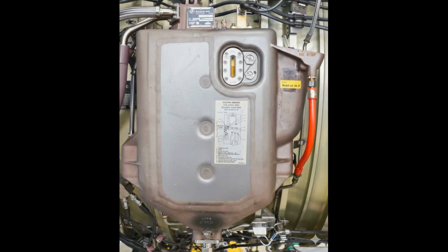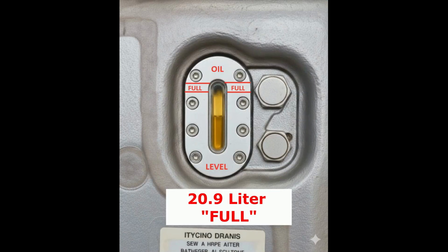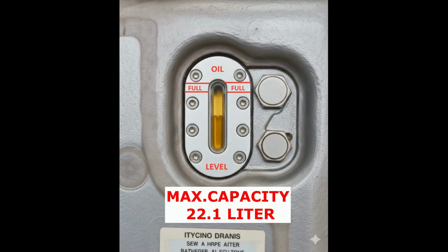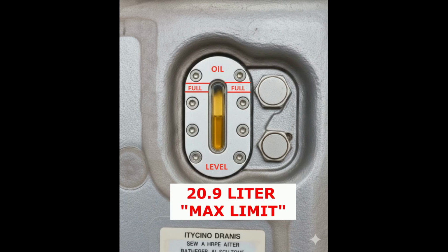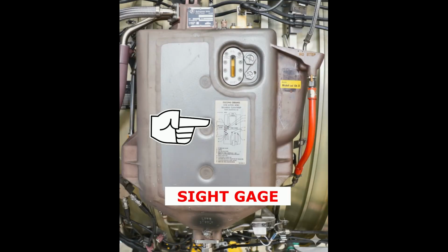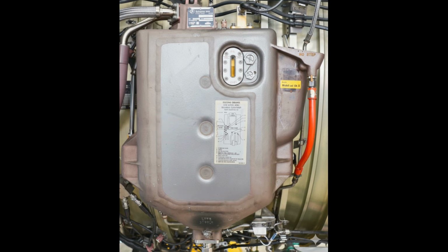Capacity and limits. The oil tank is considered full when it is replenished with 20.9 liters of oil. Although the absolute maximum capacity of the oil tank is 22.1 liters, it must not be filled beyond the 20.9 liter limit to allow for thermal expansion and proper system operation. The oil level is monitored via the sight gauge to ensure the reservoir is serviced to the required level.